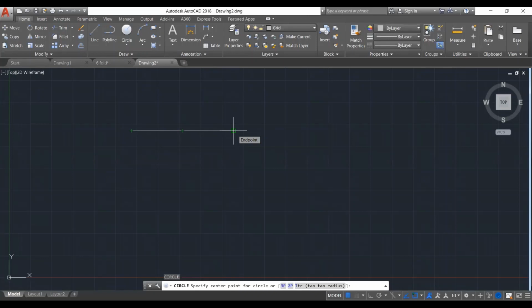So there are these options, and there are other snap settings for the intersection points and so on. This is very, very accurate because I am now 100% sure that when I choose this point, this is the midpoint, this is the intersection point, this is the end point. So how do I adjust these snap settings before drawing, to know what options I need to appear, and what each symbol means? How do I know that this triangle means it is the midpoint?